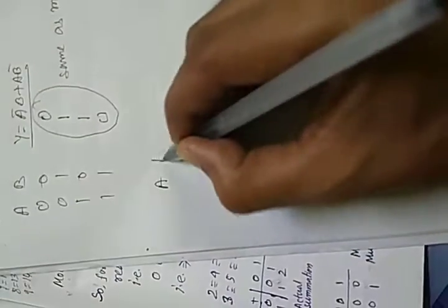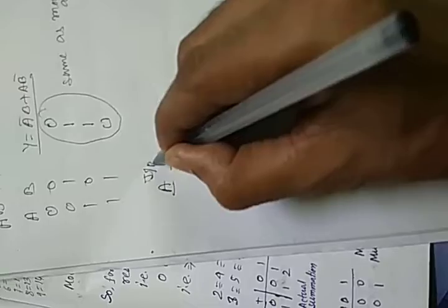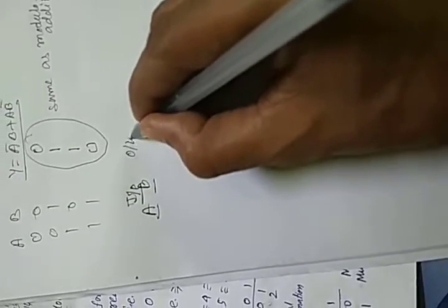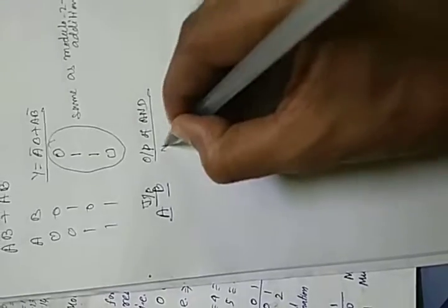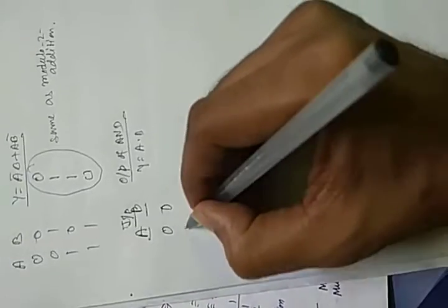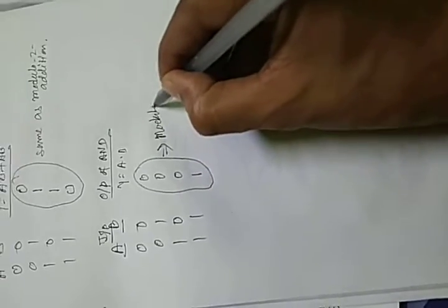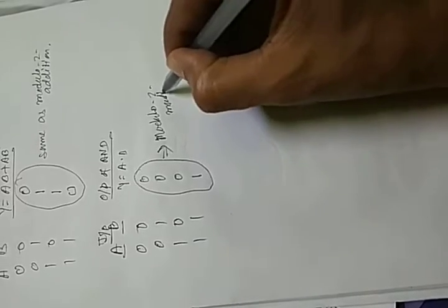This is your modulo 2 multiplication, and when you go for the modulo 2 multiplication of binary number system, the output cannot exceed 2, so there is no problem, and that is nothing but the AND operation. You know the AND operation, what is that? That is A and B input, similarly output of AND gate, that is Y is equal to A dot B, and 4 combinations are there, 0 0, 0 1, 1 0, 1 1, and output will be 0 0 0 1. So this is the AND operation, that is the same as modulo 2 multiplication, right?